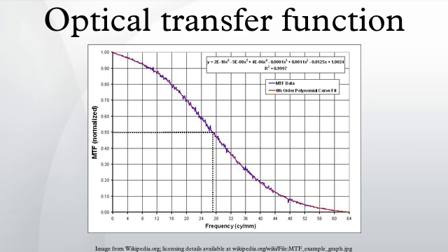This gives rise to the interesting observation that, for example, a standard definition television picture derived from a film scanner that uses oversampling, as described later, may appear sharper than a high-definition picture shot on a camera with a poor modulation transfer function. The two pictures show an interesting difference that is often missed, the former having full contrast on detail up to a certain point but then no really fine detail, while the latter does contain finer detail, but with such reduced contrast as to appear inferior overall.